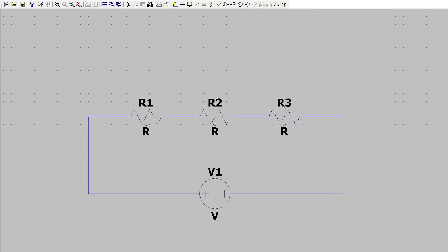To complete the circuit, we need to put a ground for reference. Then join the line also with a wire. Then let's put values to these resistors. Here we choose 10, 20, 30. This is in accordance with the example we had in the tutorial class, and we are using a 20-volt supply.